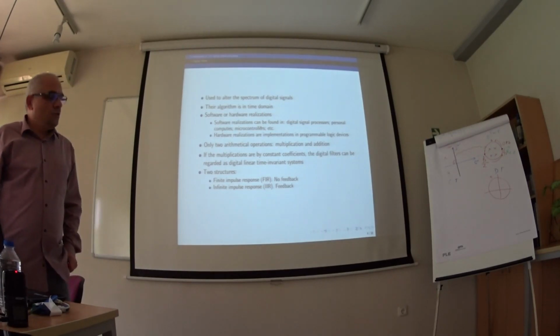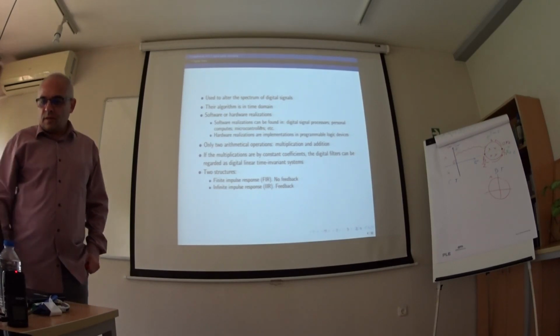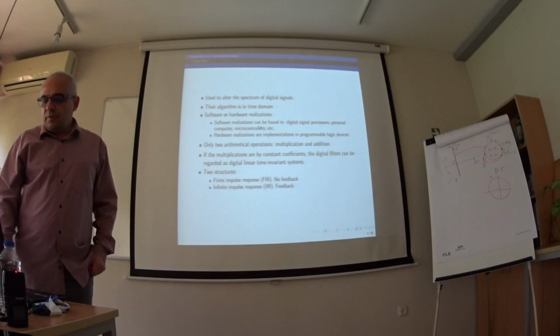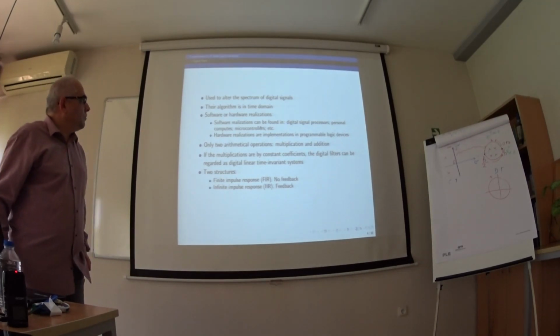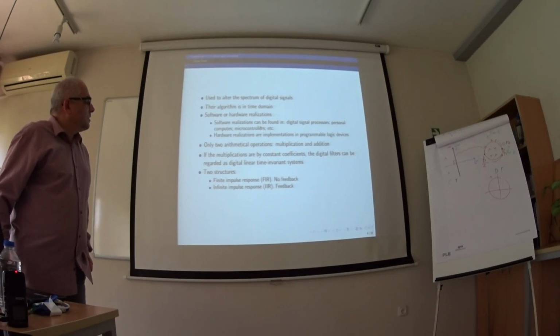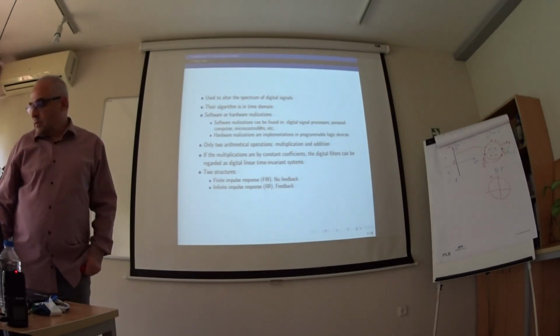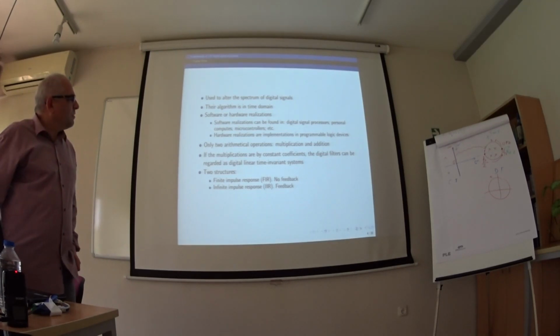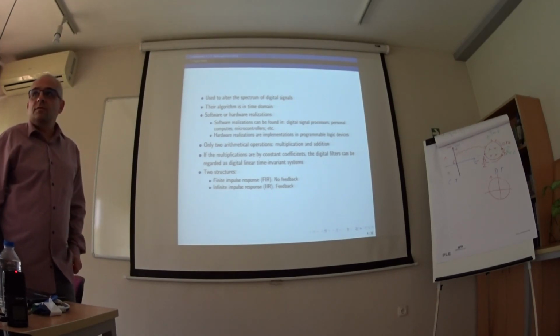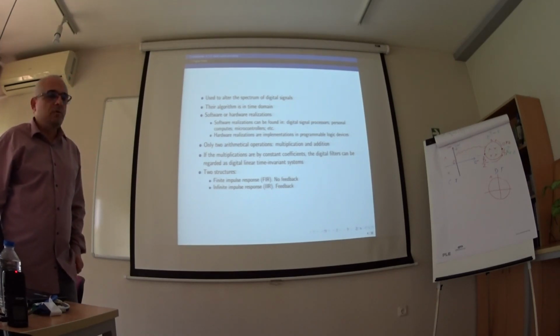Our digital filters change the spectrum of the sampled or digital signal, but the algorithm can be described in time domain. Mostly they are software realizations. Sometimes hardware versions can be seen, for example, when we implement them in programmable logic devices, FPGA or CPLD.